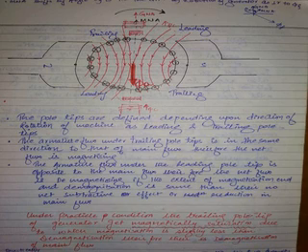The armature flux under the trailing pole tips is magnetizing in nature. And under the leading pole tips, it is demagnetizing the main flux.